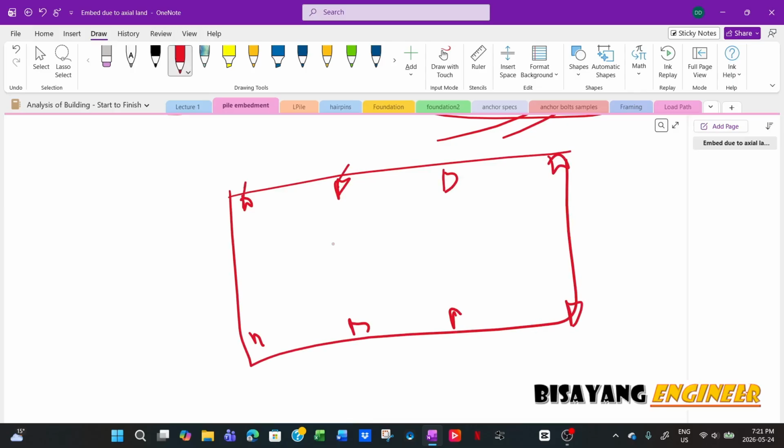Now for these piles, you would expect a large load, which sometimes depends on the span, but most of the time ranges between 90 to 120 kips, or 90 to 120,000 pounds. And for your end wall, it's even less than 10 kips sometimes.